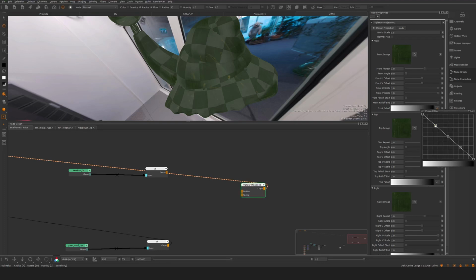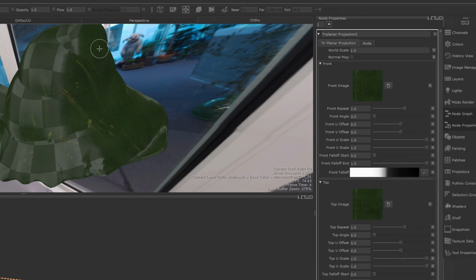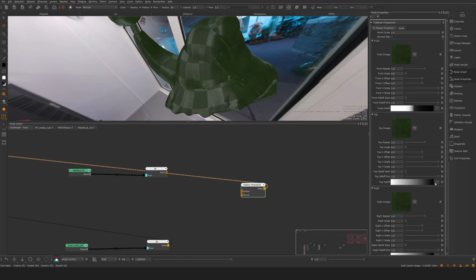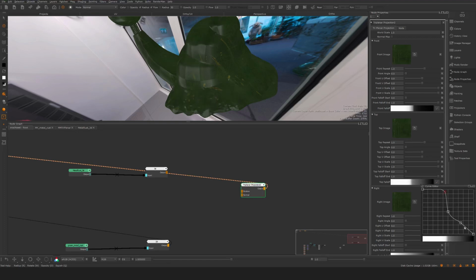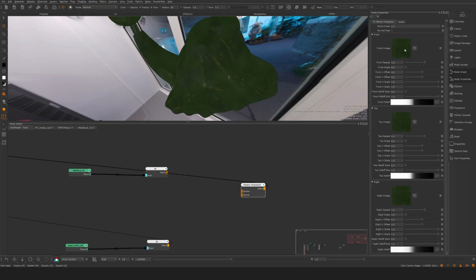You can modulate this by going in here and setting the grazing angle and the border width from the different projections. So this is something you can control, and you can start to get something that looks like it's covering everything. The problem with 3D projections and materials is they're quite tedious to set up. You have to link a lot of these things.